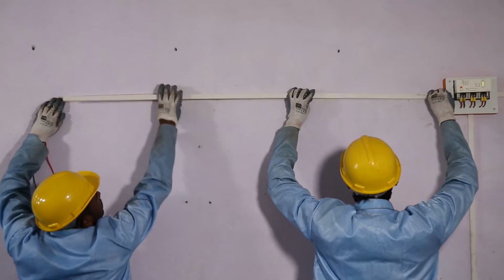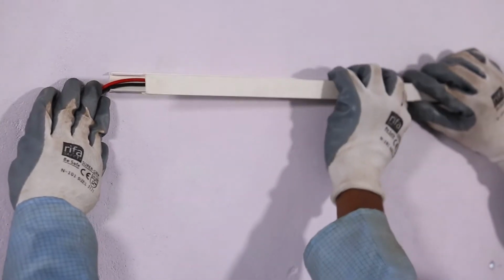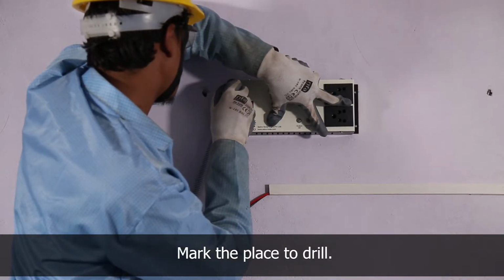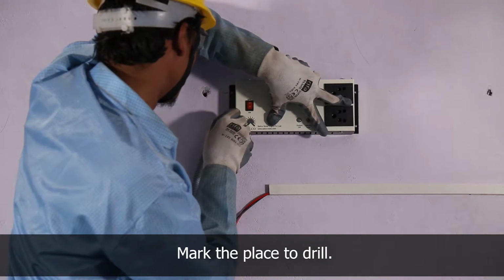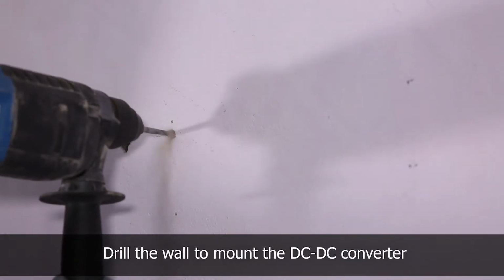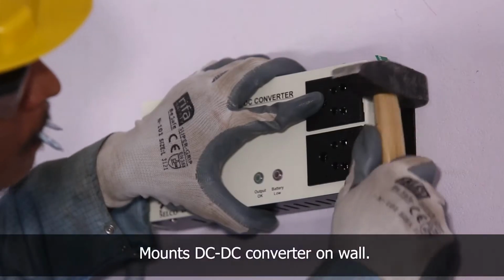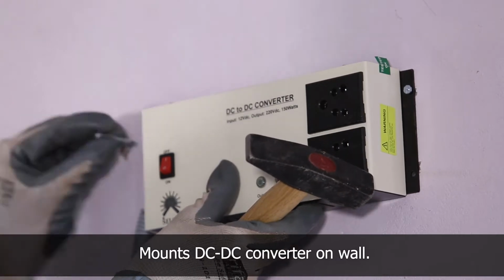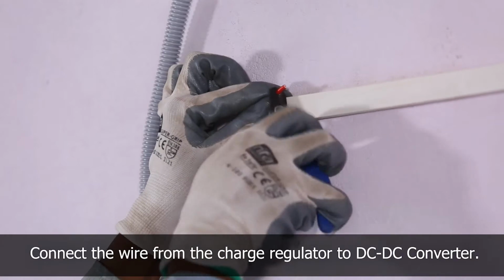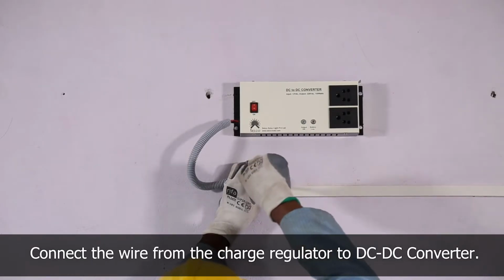The load wire from the charge regulator is taken to the DC to DC converter. Mark the place on the wall to mount the DC to DC converter and drill the wall using a drilling machine. Mount the DC to DC converter on the wall using a couple of nails and a hammer. Strip the load wires from the charge regulator and connect to the DC to DC converter.